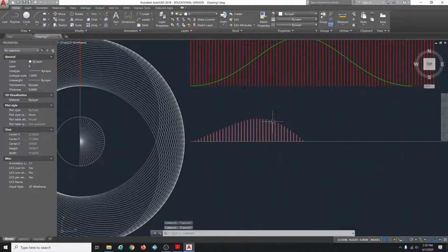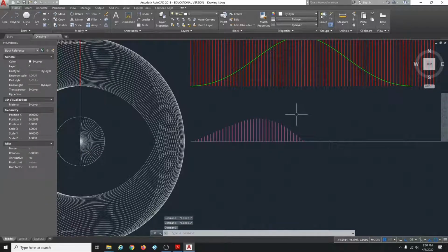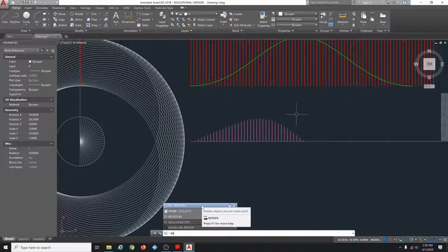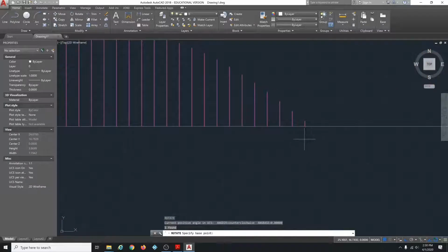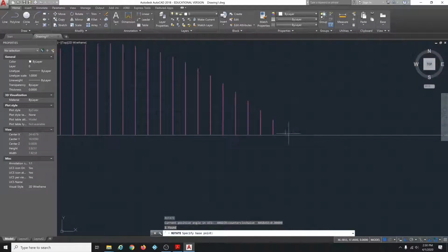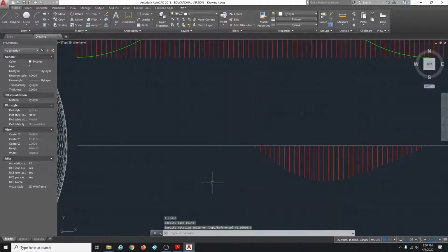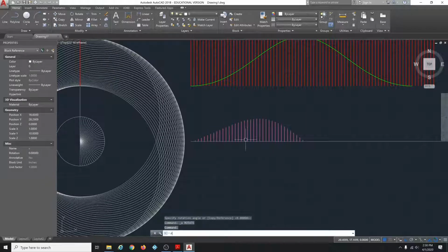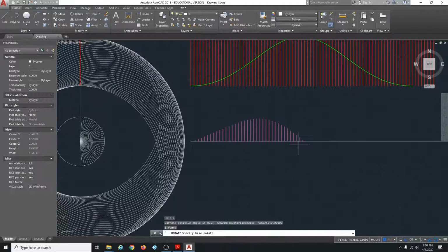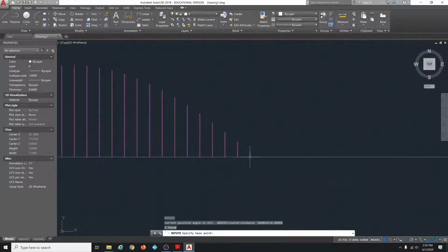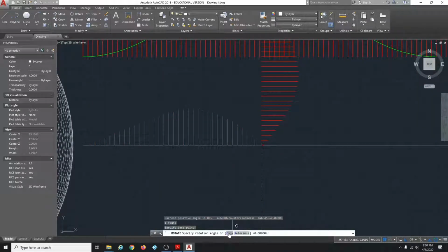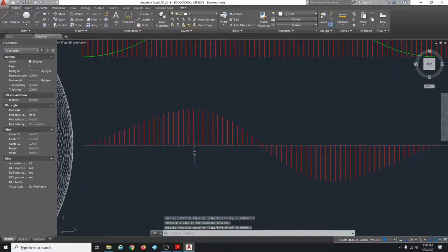That's our velocity data. So let's take that, and we need to mirror it twice, which turns out to be the same as a rotation. So do a rotate about this point, and I have ortho on, so it's doing these 90-degree things. So right there, Control Z, and say this guy, rotate, base point, this end point. Okay, I forgot to click copy. Click copy, 90, there we go.